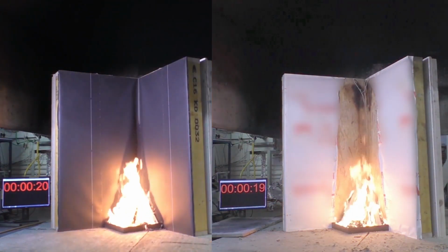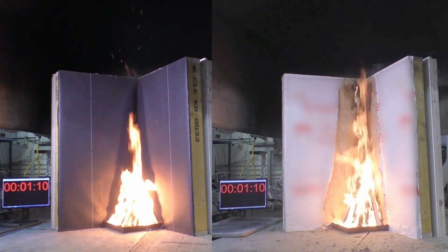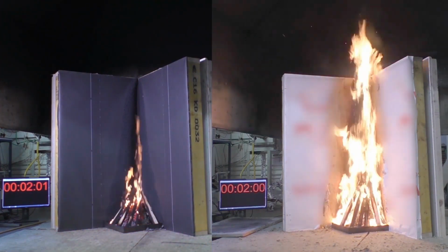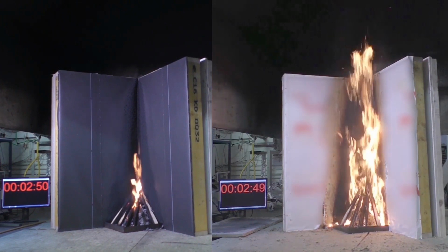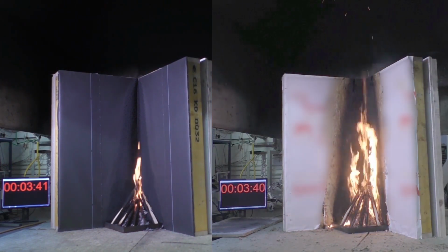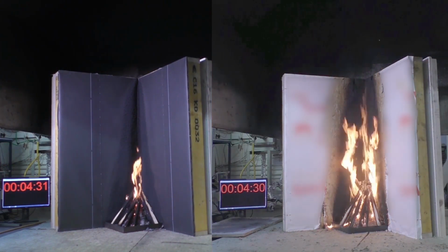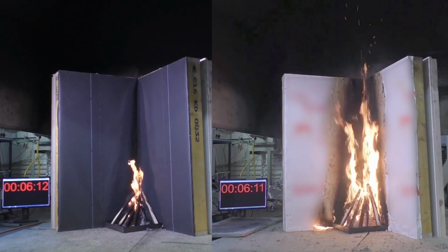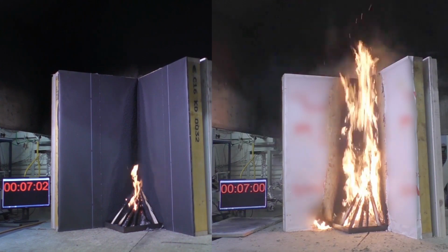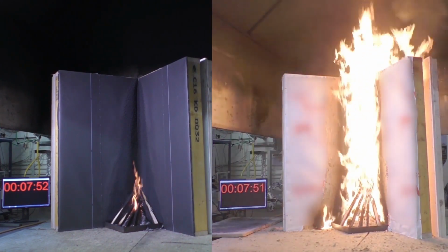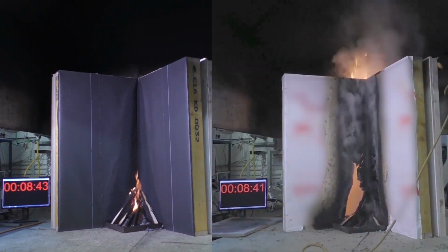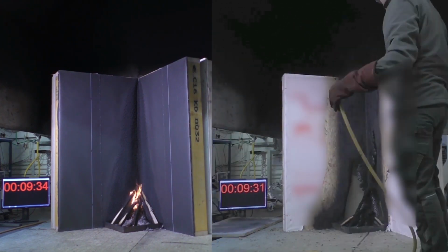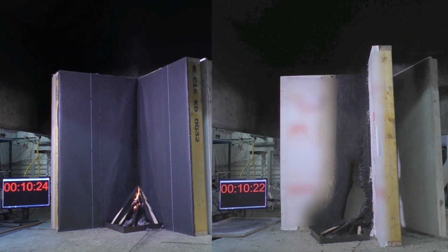In this comparative test, based on the EN 13823 single burning item test, the fire shield on the left reacts substantially less than the other Class B fire resisting membrane on the right. The surface of the fire shield acts similarly to an intumescent coating, frothing up to protect the insulation boards and structure. In this test, the unique coating protects the sheathing long enough for the external fuel source to be exhausted and the fire to self-extinguish.